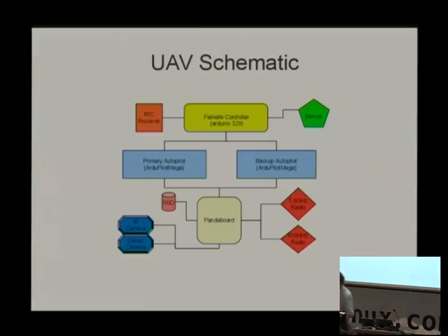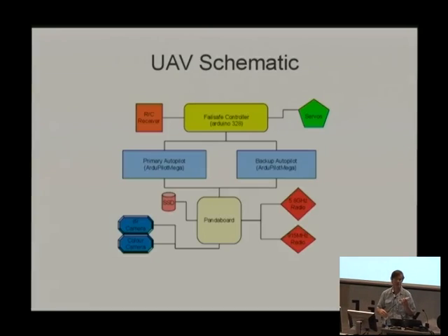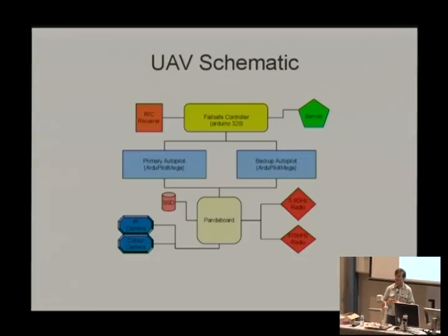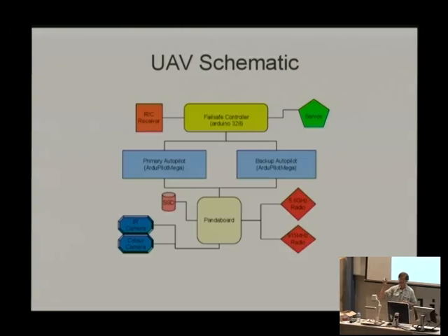One at 5.8 gigahertz, which uses this sort of radio technology. This is a Ubiquiti Bullet, a 5.8 gigahertz Ethernet bridge. It can range from about 1.5 megabit up to 100 megabit type link. We ran it at its most conservative settings, known as MCS 0, so you're running it at the lowest possible speed for maximum possible range. And then we had 915 megahertz radios, which are these types of little radios. The first half of the talk is really about the development of the firmware for these radios.